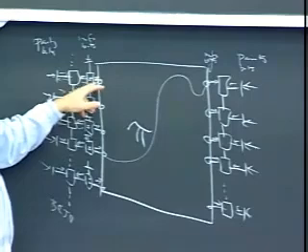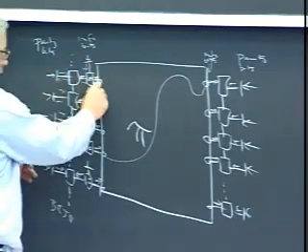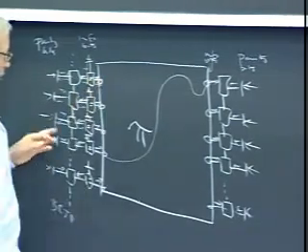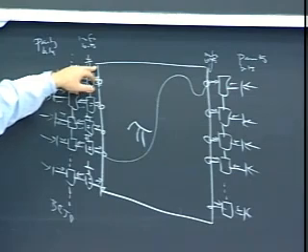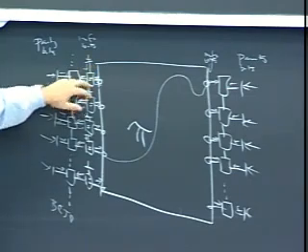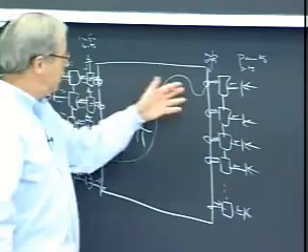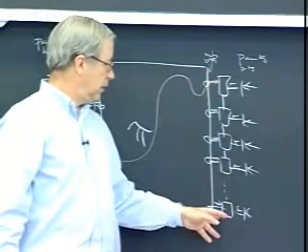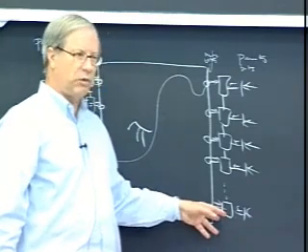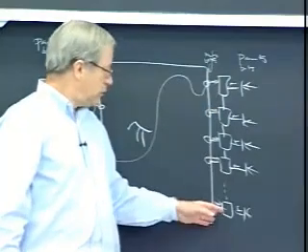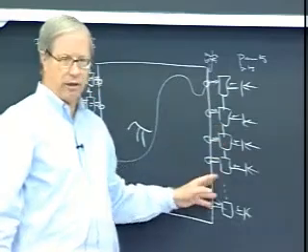Okay, now we have more over here. We still got the same intrinsic information coming in here, but now we can take this new extrinsic information and combine it with this intrinsic information and hopefully get an improved, higher quality information, because we've incorporated all the information from all these received symbols on this side, and we send that over here. If you think of it in signal-to-noise ratio terms, as some people do, you hopefully have improved the signal-to-noise ratio in your information that's coming over. It's as though you received these bits over a higher quality channel.